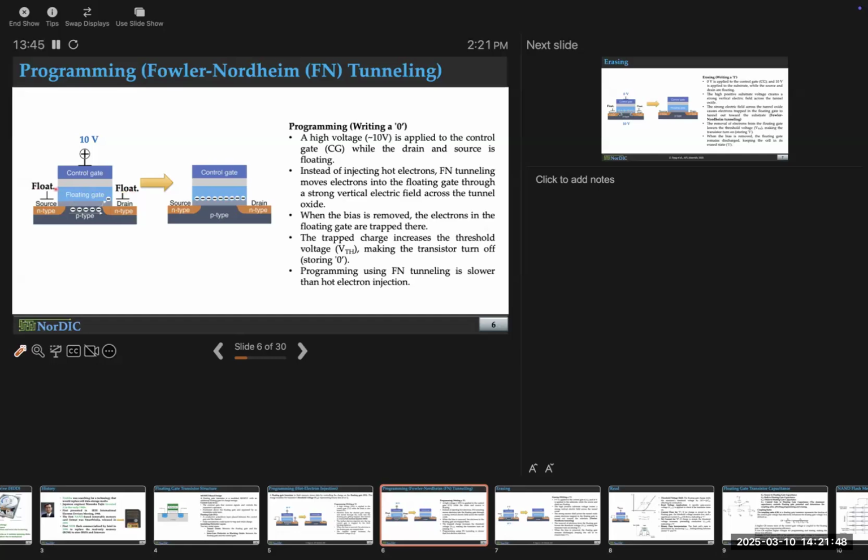Notice this is float. So they're floating. You basically just have electrons lying around here and you attract them, they get stuck. Typically, that's a slower process because what you rely on is minority carrier generation. I'm not getting into the detail of it. But basically, you wait until the electrons come and show up here and create a bridge. That's all. You don't channel them from here to there. They just come and gather around, and then you just grab them like this. Okay. So there are two reasons why both of these approaches are used, but this one is obviously slower.